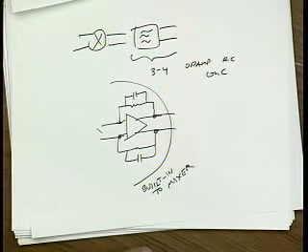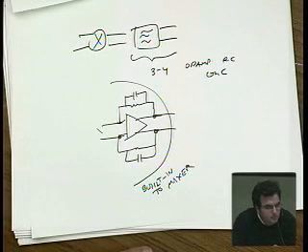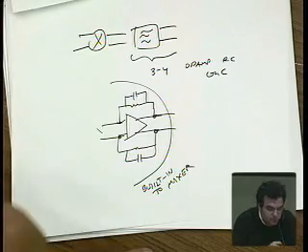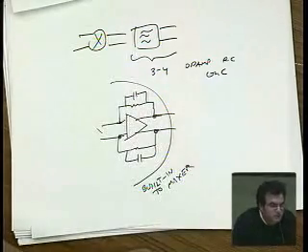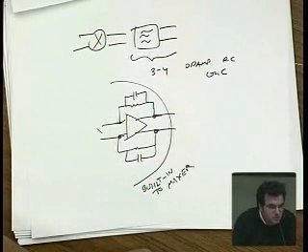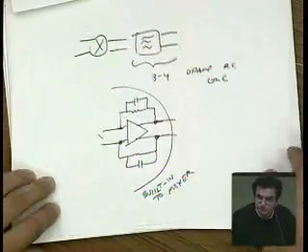Yes, question. So in this passive current commutating mixer that we were discussing, what will happen if we don't plug in that op amp in the last stage and just put simple resistors to convert that current into voltage? Then we don't get the advantage, right? We want to go into a low impedance node so we don't get voltage swing at the output. But it'll still work, yeah. Effectively, then it looks like a Gilbert mixer, right? We haven't really won much if we do it that way.